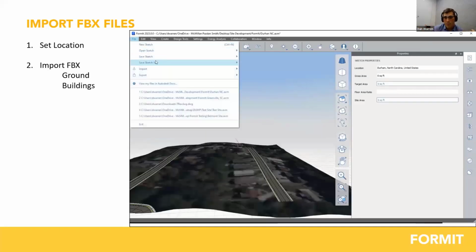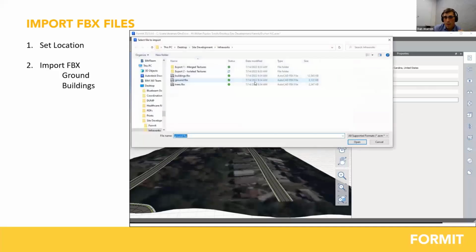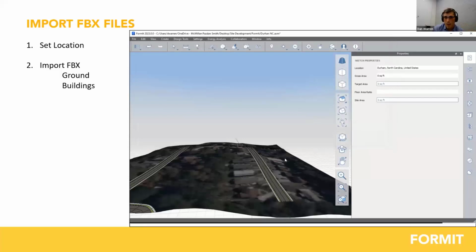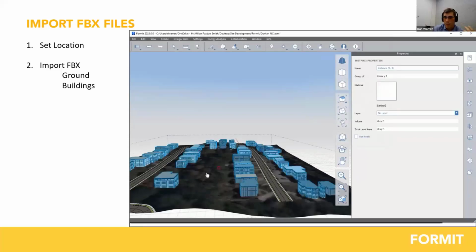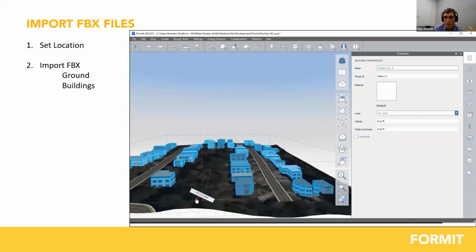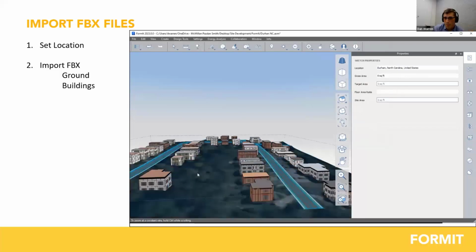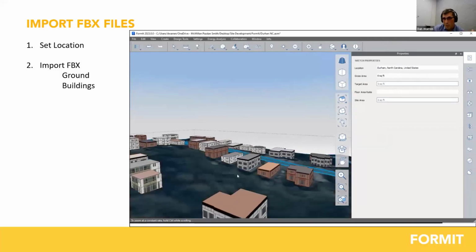And then the next thing is bringing in my buildings. I go ahead and just import the buildings, and bingo, bango, I should have buildings that appear. There's my buildings. What I like about this is everything's using the same origin, so alignment is super easy. You just have to remember to hit escape after you bring it in. Otherwise, you'll place it in the wrong spot.